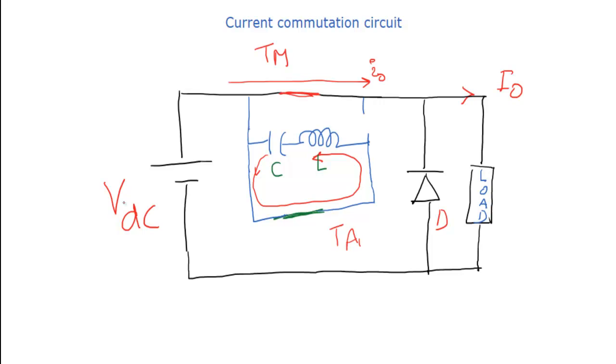Okay. Now after that, the inductor, which was already charged by the capacitor, will start discharging. That is nothing but this capacitor being charged in this way. That means the inductor will still discharge in the same direction as the charging current. So the current is the same. The energy is now transferring back to the capacitor, but this becomes the positive plate and this becomes the negative plate. So this keeps going like that.